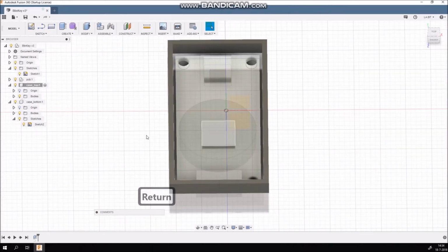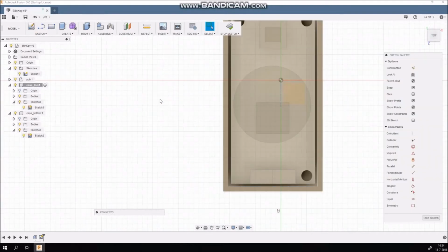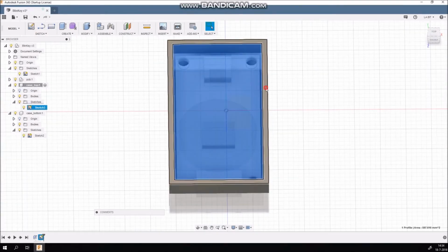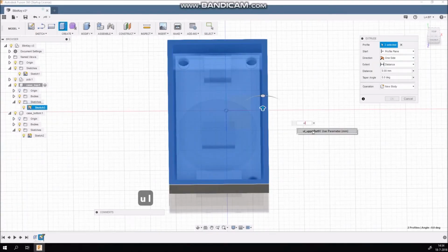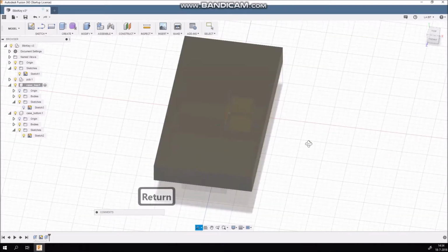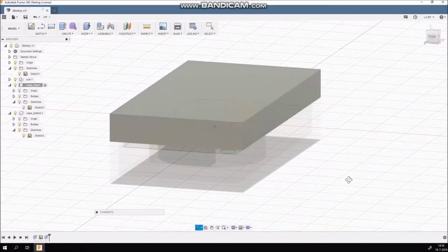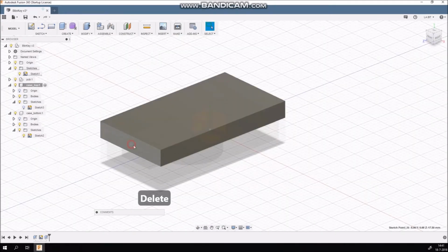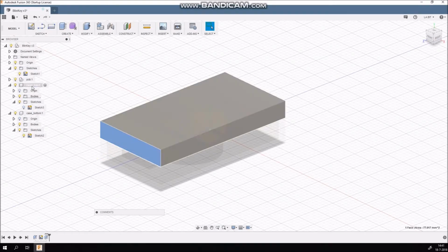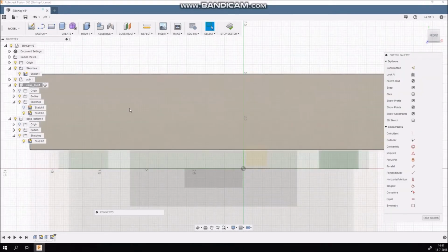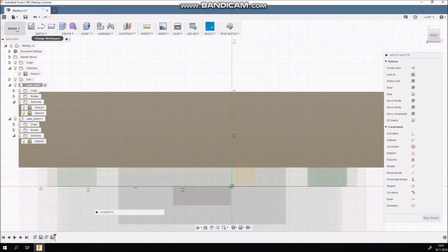Again, select the outer shell of the upper part and make a new sketch. Leave the sketch, select the inner part of the upper part and the outer shell and extrude it for the thickness of the casing. I'm going to make a hole on one side where the headers are. Therefore I select the middle and, well, make 4 areas like this. You could actually do it in one time, but I didn't do it here.